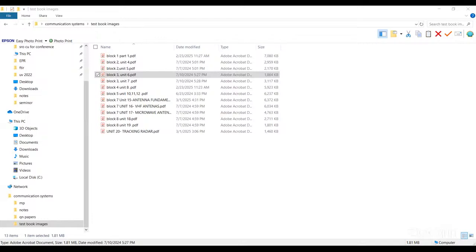PF is the forward power. In the same way, directivity is also calculated. What is the formula of directivity? D = 10 log10 (PF/PB). You have to write this. Actually, the backward power PB is equal to 0.